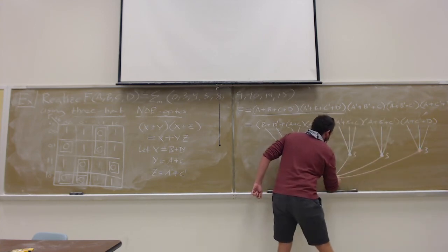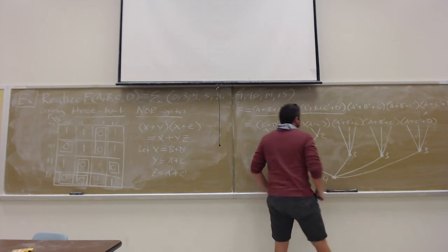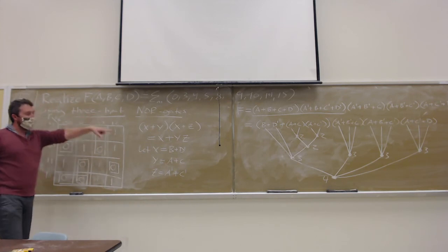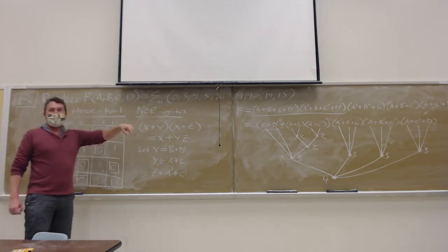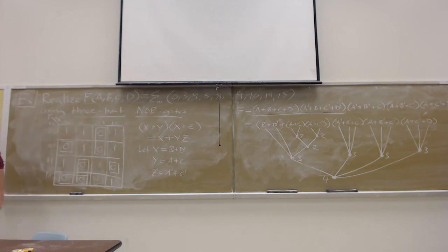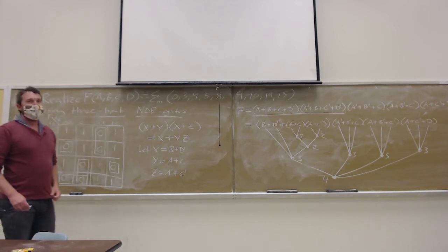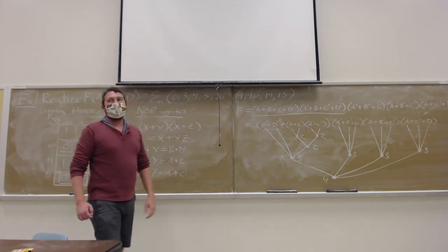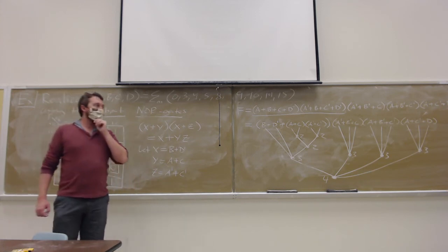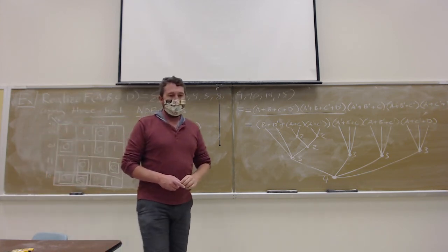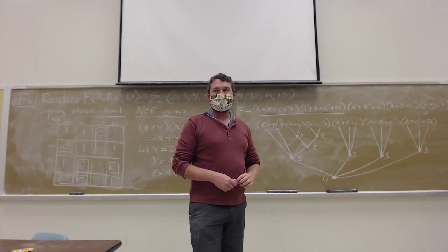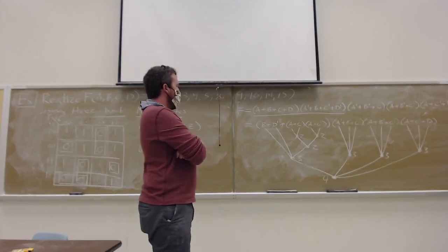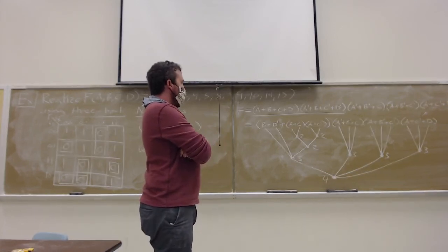What's the problem? Problem is that it has 4 inputs. All right, and we're still limited because that last AND gate is going to get converted to an OR gate as well. It also can't be more than 3 inputs. Which means we got to eliminate one of those other terms to bring the number of AND inputs down. So what can we do? A or C prime. Okay, what would you get?